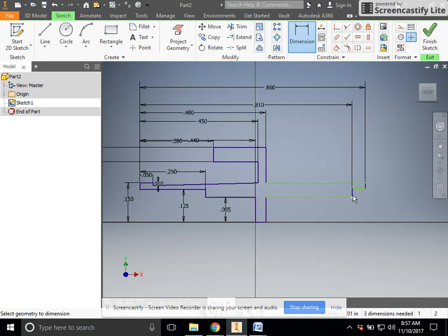And then these over here, we got 3 more. We need to know how high these go. These two look like they should be the same line. So we're going to use the collinear constraint between these two lines, and that will lock in that one. And then we're not sure, but it looks like this one and this one over here should be collinear. And so we're just going to go ahead and make those two collinear also.